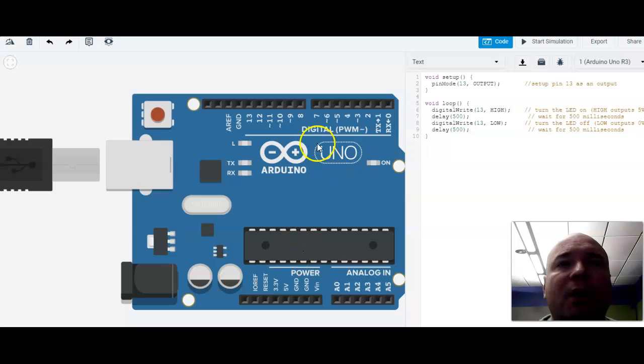And you can see in our environment we have added our board, and on our board we have our power. Once we plug in the power, any program that is currently stored on our little microcontroller will start running, and it will continue running until we unplug the power. The code stays on the board even when it's unplugged. This is stored in what's called flash memory. Flash memory is what's called non-volatile, which means when you remove the power from it, the memory stays. And when we add the power, then that program will start running.